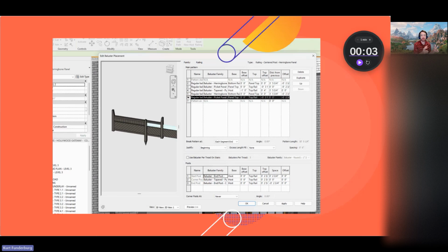These are set up as panels, which are another thing, like if you've done glass panel railings, where every so often there's a baluster, but most of the railing is a panel. This is a lot more complex because it's dealing with the overall length of the rail, and then I'm wanting to half that, and that's where the mid baluster sits, and then I also have the panels within that that are justified. This allows us to have that middle pyramid cap right in the middle, and then I'm figuring out the dimensions for the panels to make sure that those fit.